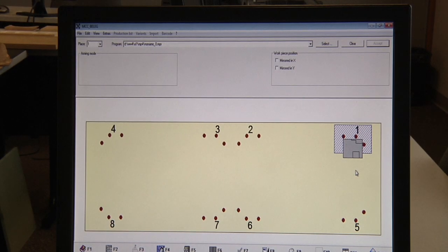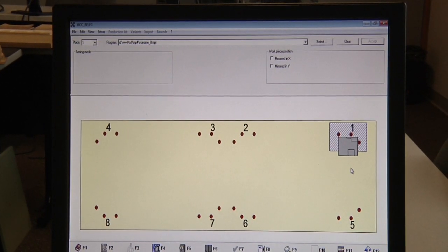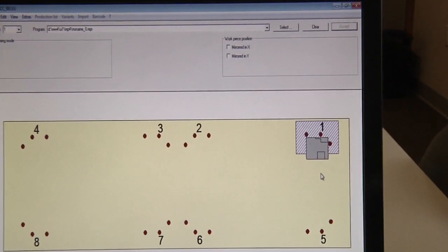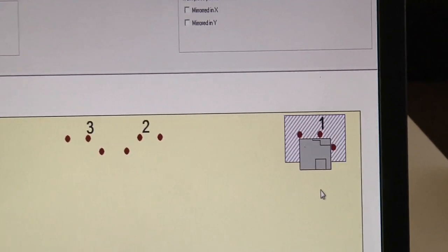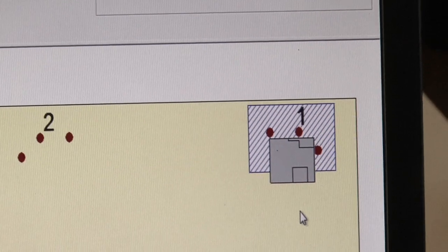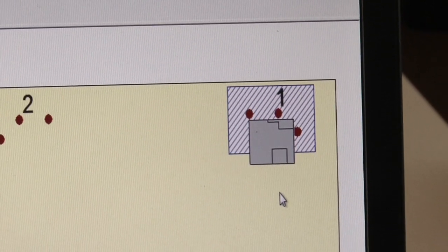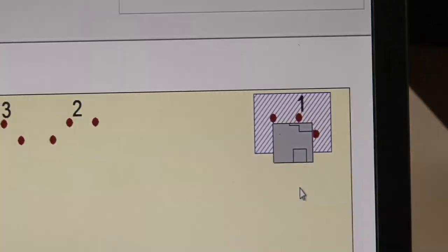It will accept this part as being an inch program in a metric field. So there's two things we could do. We could actually scale the drawing into metric, use the metric conversion profile, or we could leave it as inches and just make sure that our tooling will convert properly when it rounds from the decimal inch into the metric.